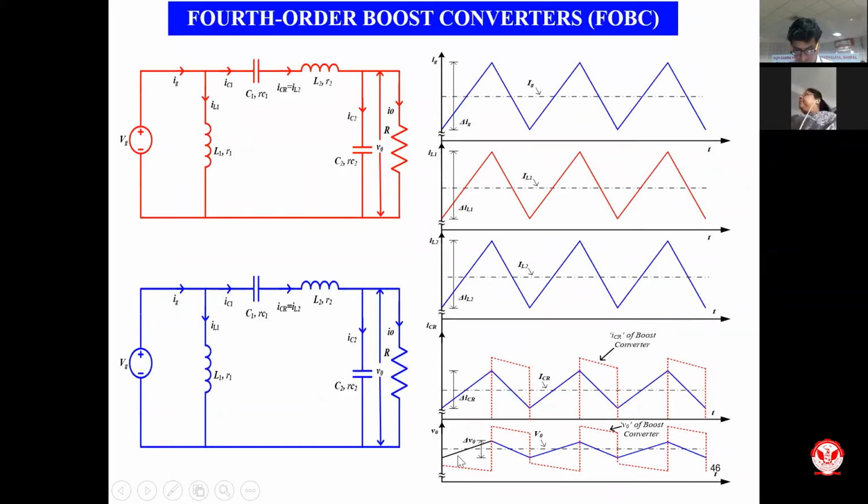And also you can see the waveform of the voltage. What you see is that the load voltage had higher ripples, hence higher EMI, in the case of the conventional boost converter. But in this case, you have a continuous load voltage, which is desired. So by adding one inductor and a capacitor, you could drastically improve the load side performance of your conventional boost converter.